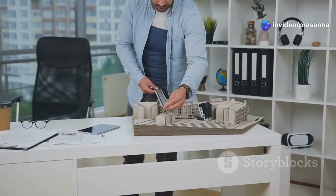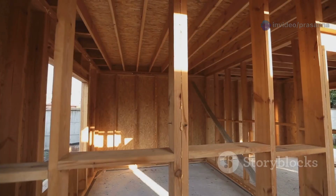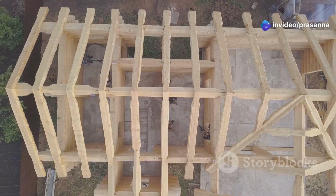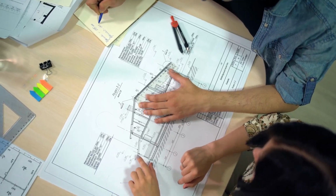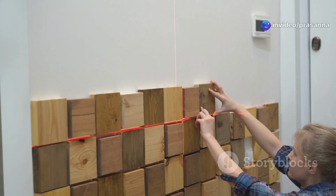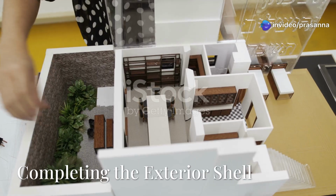For multi-story houses, the process for upper floors is similar. You will first need to complete the walls of the lower floor. Then you can create the ceiling of the lower floor, which also acts as the floor for the level above. You can draw a large rectangle over the top of the ground floor walls. Then use Push-Pull to give this slab its thickness. After creating the upper floor slab, you can import or draw the 2-dimensional plan for the next level on top of this new surface. Then repeat the wall building process. Remember to create openings for stairs between floors.